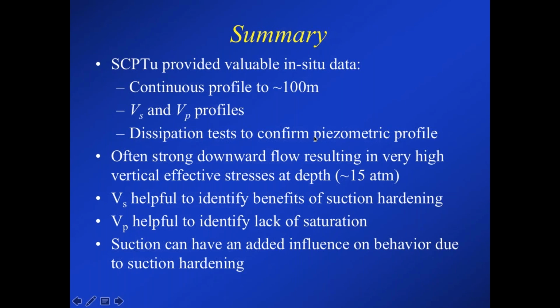And dissipation tests were carried out, lots of them, and they confirmed the piezometric profile, a strong downward flow, significantly less than hydrostatic, supporting that it's predominantly unsaturated, which is supported by the P wave velocity measurements. So a strong downward flow resulting in very high vertical effective stresses at depth, and shear wave velocity appears to be helpful in identifying the benefits of this suction hardening, and the P wave velocity was helpful in identifying and confirming the lack of saturation.